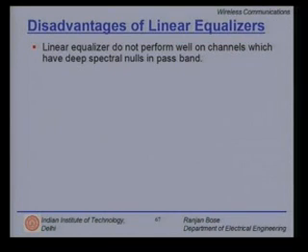After all, what is an equalizer doing? It is trying to make an inverse filter, undo the effects. So, in the frequency domain, wherever there are deep nulls, which there are in most hostile wireless channels, it will try to have a very high value in the frequency domain, thereby giving a lot of importance to the noise present at those frequencies. It will amplify the noise immensely.